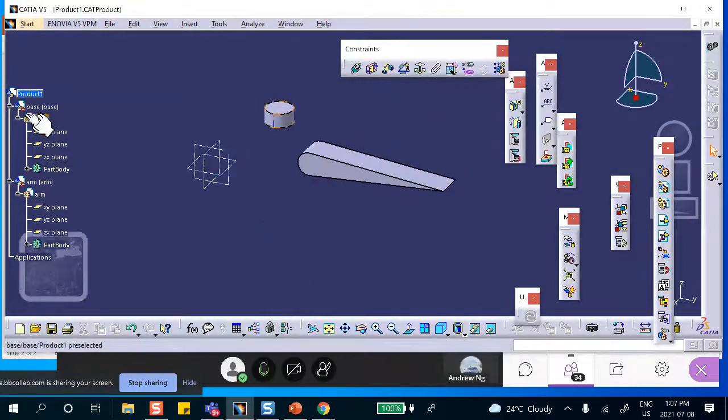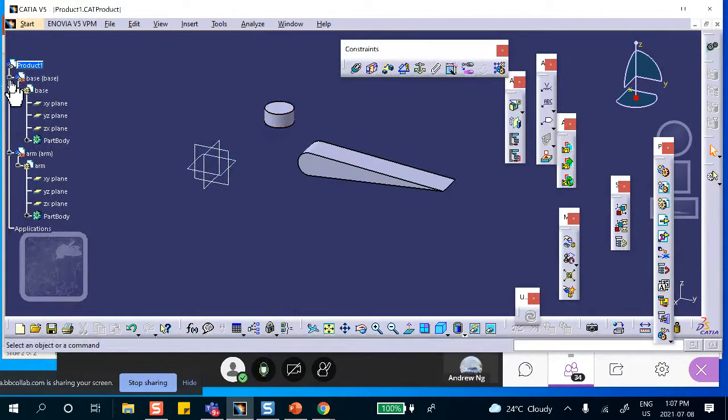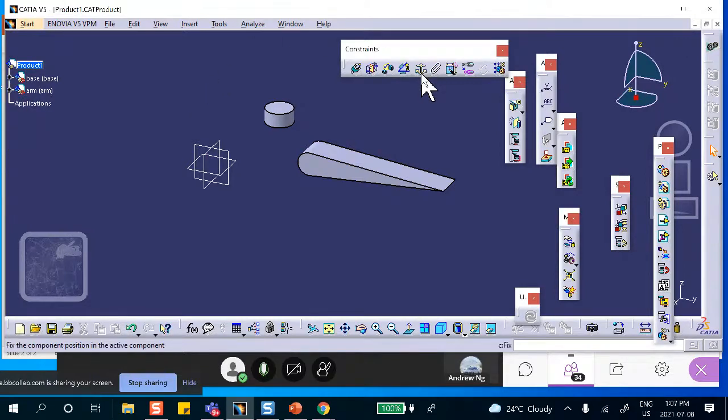All right. Now we're going to create assembly constraints. First of all, I suggested to you that you always fix something that is the most reasonable item to fix. That's going to be the base. Anchor that, and it puts an anchor there. Whatever constraints you put in there, that piece is going to stay put in space. These guys will move. In this case, this will move when I put a constraint, but that will not.